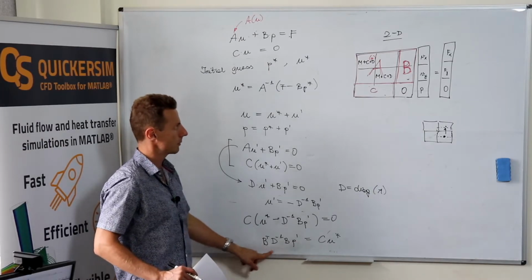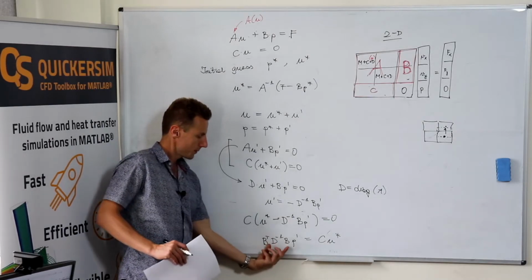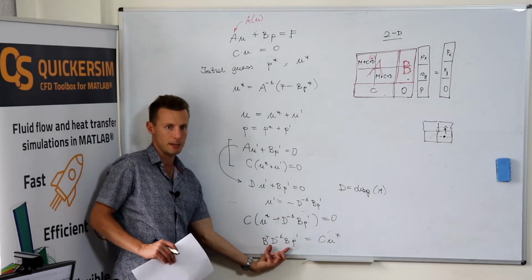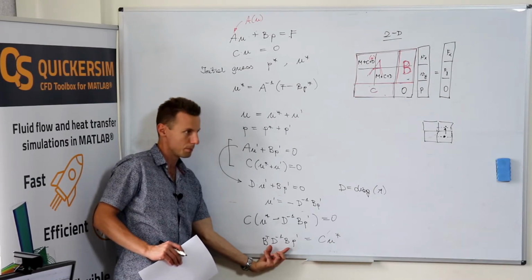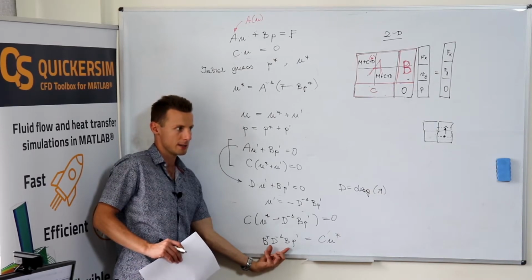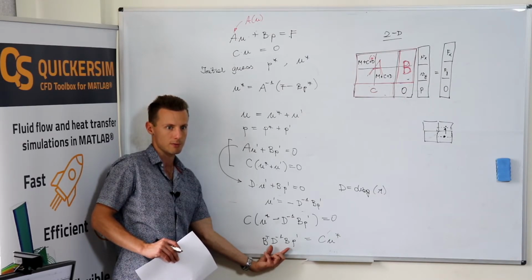We can multiply it by B, and it's still a cheap numerical operation. So we can explicitly build the matrix B transpose D minus 1 B, and it has nice numerical features. It's symmetric, positive definite, so conjugate gradient methods, etc., will work. You can even find very efficient preconditioners for symmetric and positive definite matrices.